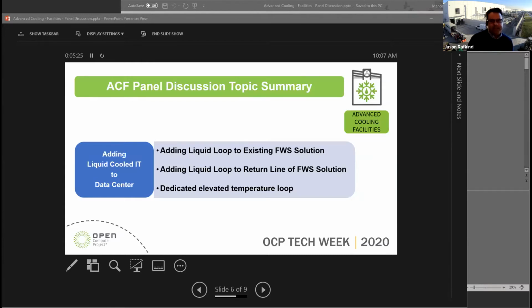What we've done is modify our chilled water design, our loop, a little bit, and we're starting to pre-position taps in our mechanical galleries. In those galleries, we can use a CDU and transition directly to the liquid cooled solution fluid, and then leave it to the manufacturer, the proprietary solution, to handle the liquid in the medium in the data hall.